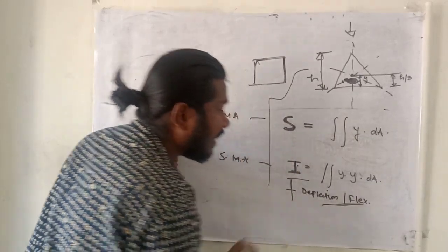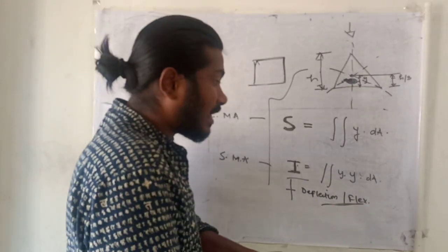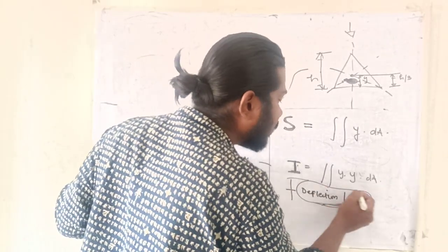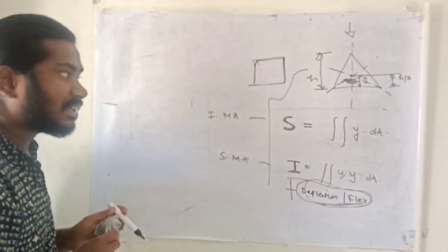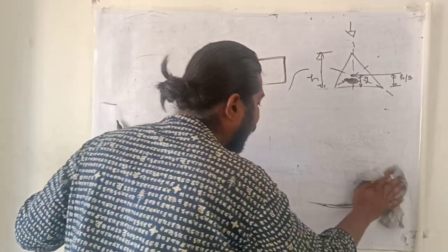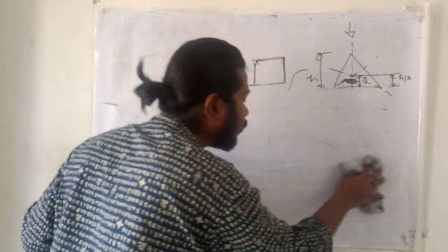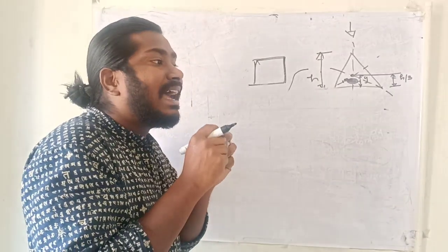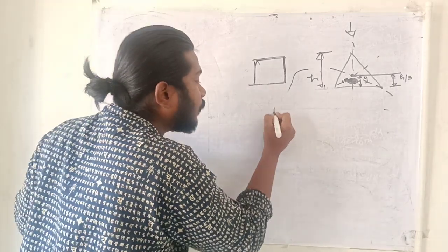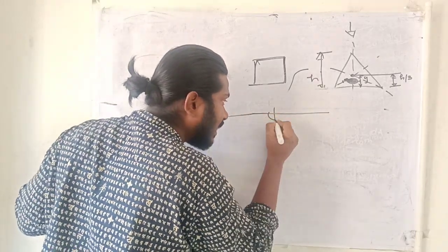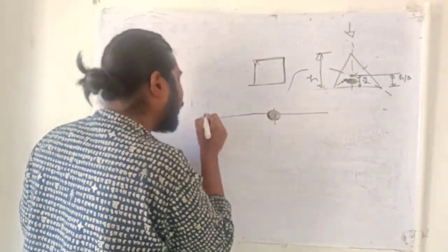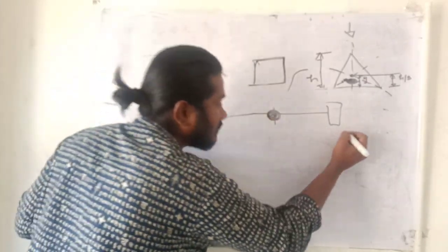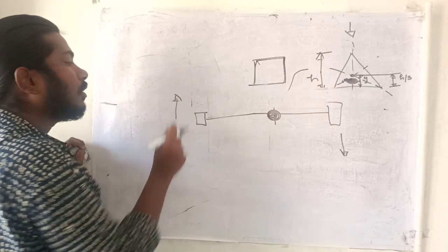This shows the flex. The higher the value of second moment of area, the lesser the deflection is going to be. Similarly, for our vehicle, we have to increase the second moment of area. Yesterday we discussed this. To have a higher value of moment of inertia, what do we have to do? Rather than having all the objects aligned towards the centroid, we have to move them far. If these objects are moved far, the pitching down of the vehicle could be reduced.